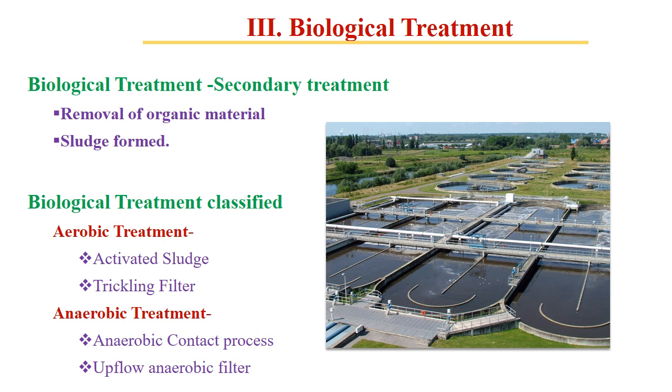This can be done through activated sludge or trickling filter. And then there is anaerobic treatment, in which it is done in a closed condition, so there will be no oxygen. Here it may be done through the anaerobic contact process or upflow anaerobic filter.